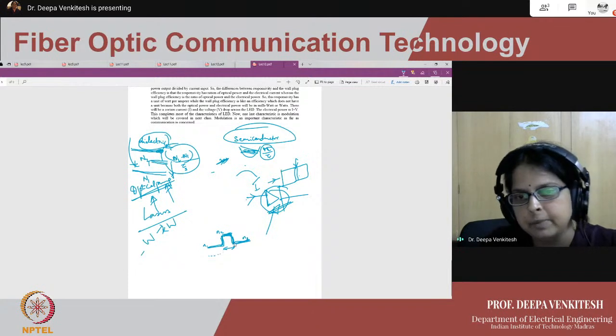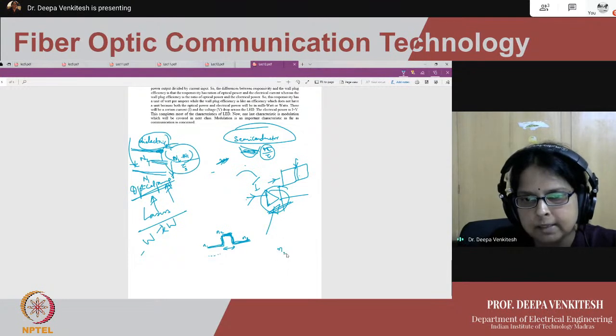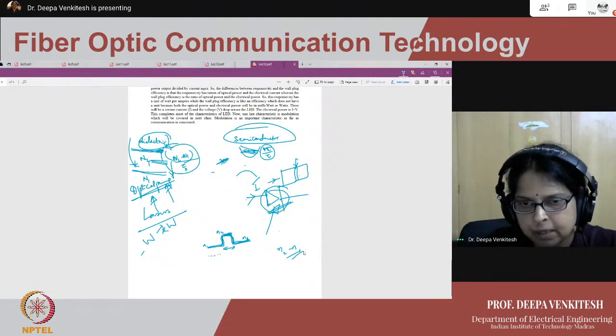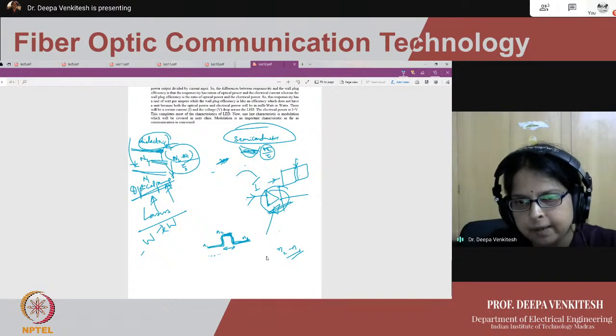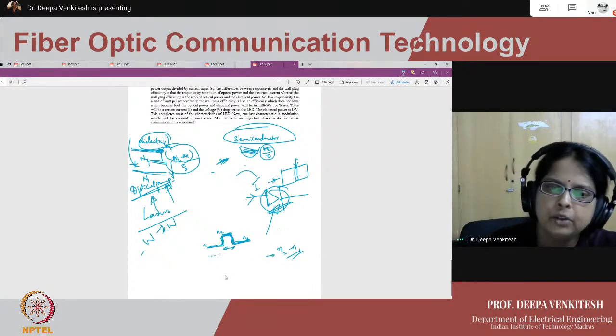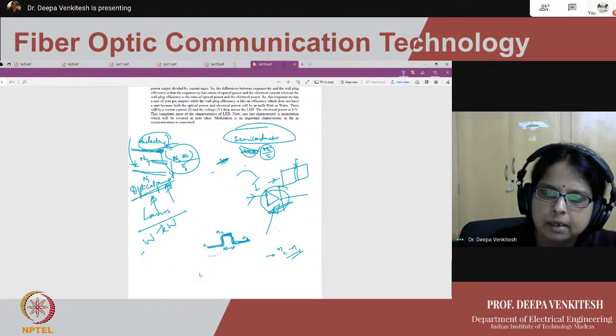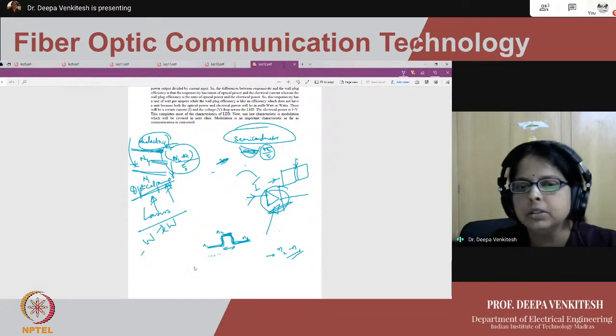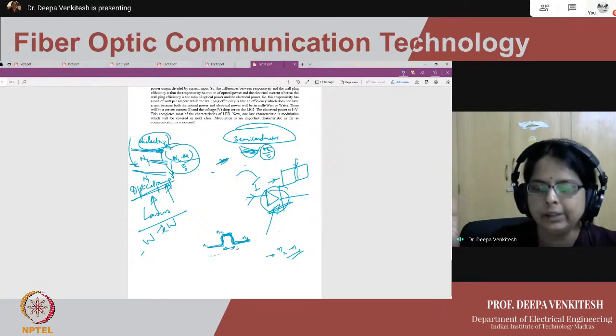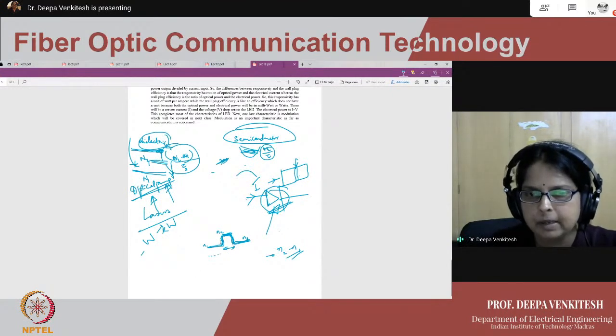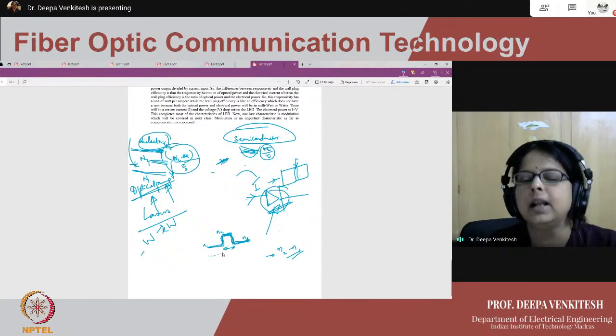This is the width of the depletion region. Now the next thing you are able to control is this N2 minus N1, where N is the refractive index, and you are able to control the refractive index contrast, delta N. Now what happens for different refractive index contrast is that you will learn later, but I'll give you a primer. We learned about longitudinal mode, which is the mode along the length of the propagation of light. But from an LED structure or from a laser structure, there's something called a transverse mode, which you would have come across if you have learned waveguides.